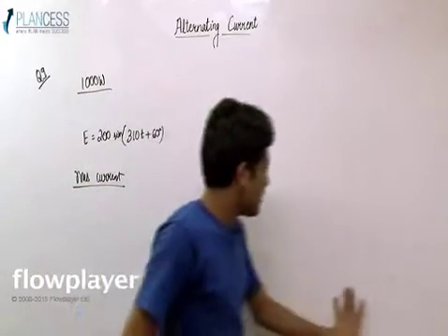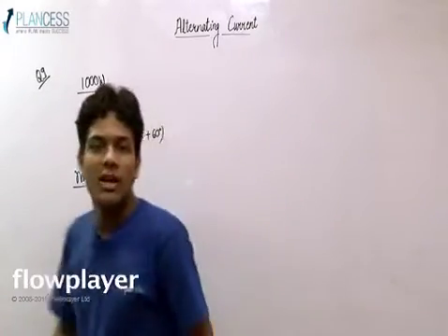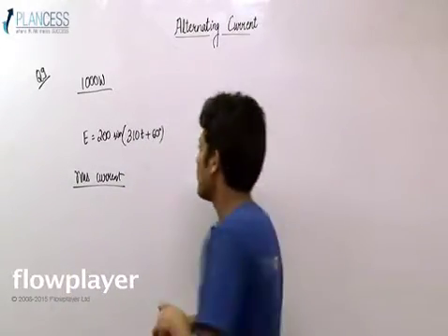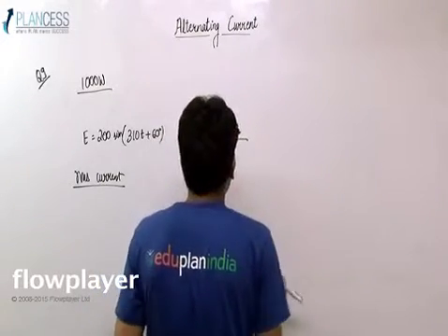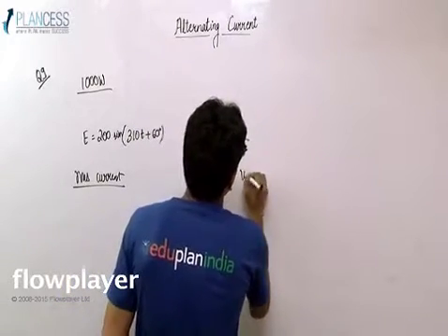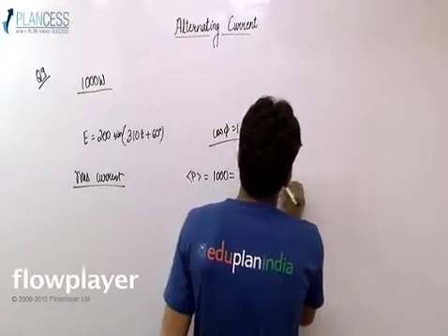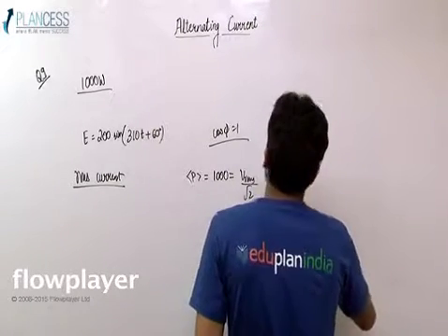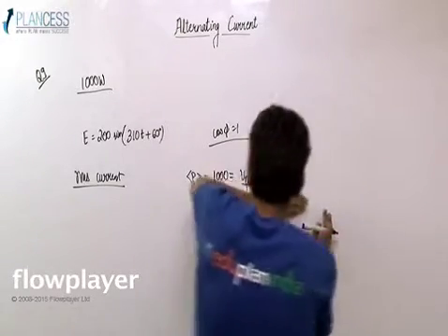You have to tell us the value of the RMS current through the lamps. So firstly, understand that a lamp can be considered as a resistor. For a resistor, the power factor, that is cos phi, is 1 because the power factor angle is 0. So the average power, 1000 watt, can be given as VRMS into IRMS.